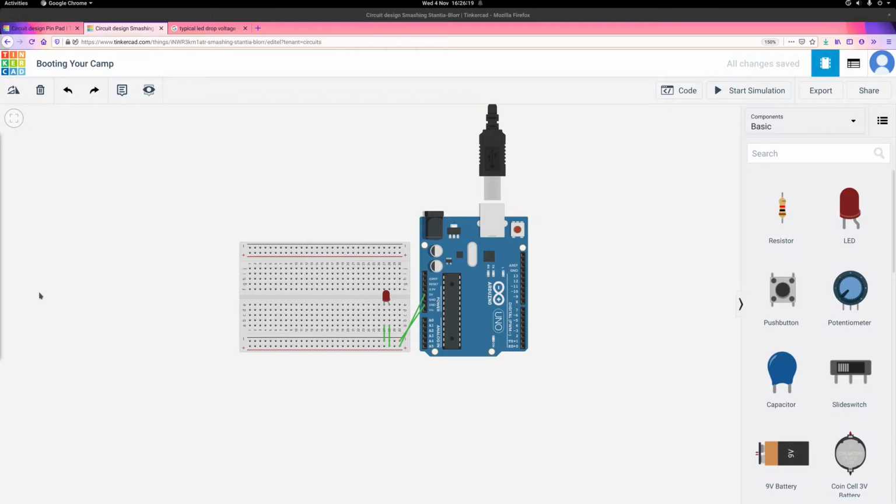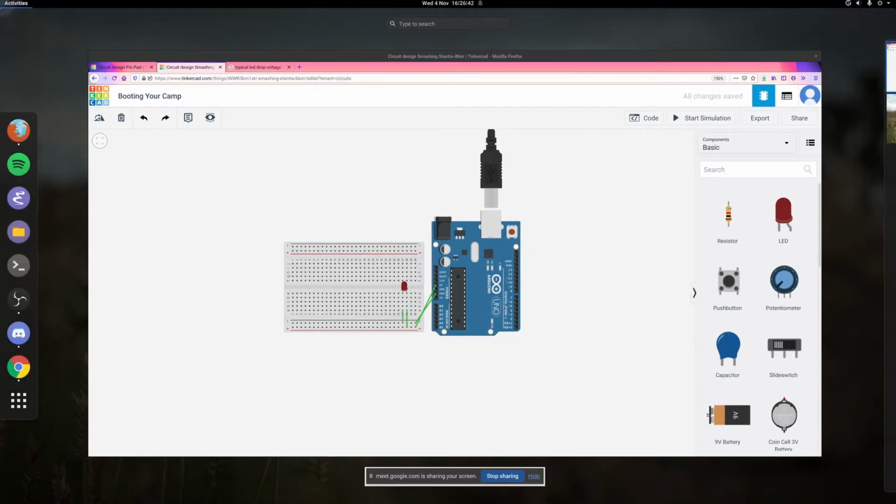Wonderful. Now that we have our 3.3 voltage, that's the voltage we want in Ohm's law. So we know that it's going to have 3.3 volts across it, and we also know that we want 20 milliamps to go through it. So we have the voltage, we have the current, all we need to calculate is the resistance. So I'll let people give me some resistance values from that calculation, and I'll give you all a second to do that.